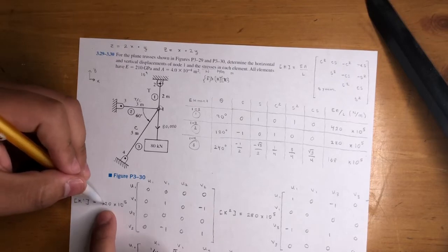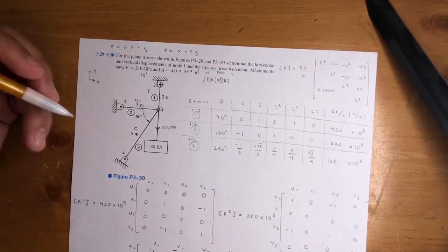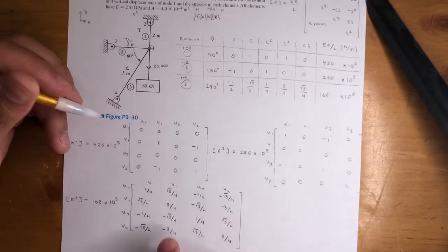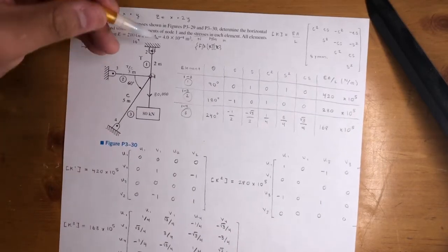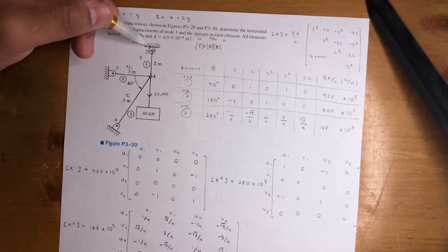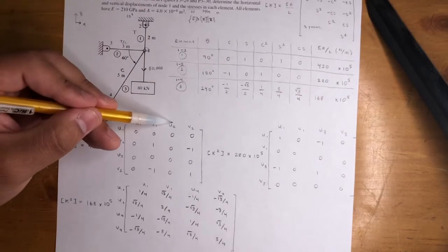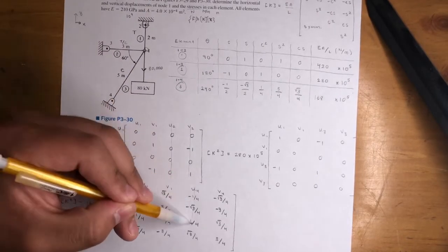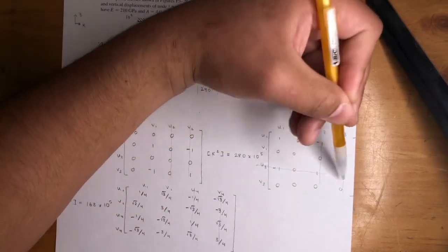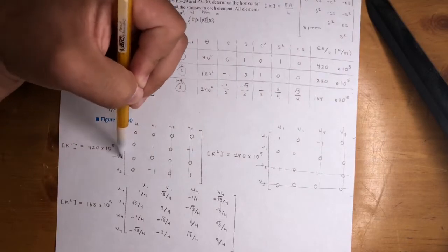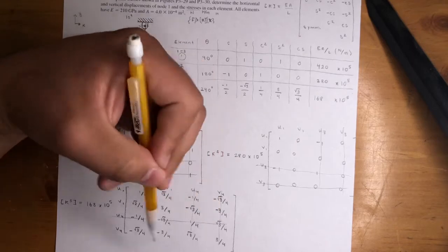Check it out. We're going to put this 420 and multiply it to the whole matrix instead to get rid of it here. We could do that now, but it's going to be a lot of work to do for every single number. So what we do is first we apply the boundary conditions. U2 V2 is fixed, U3 V3 is fixed, U4 V4 is fixed. So anything U2 V2, U4 V4, U3 V3, they're all gone, and same for the rows. So all this stuff is gone. We don't care about it. It's fixed. It's not going to affect us in any way once we do the calculations.